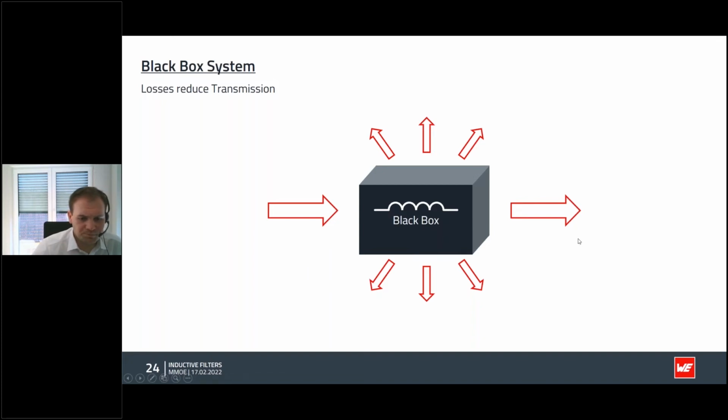So again, the actual mechanical construction of the PCB and of the housing of the PCB will have some influence on how much current this SMD ferrite will be able to carry without getting too hot. So this will happen to a differential mode signal going through the SMD ferrite. So we will have some kind of attenuation here.